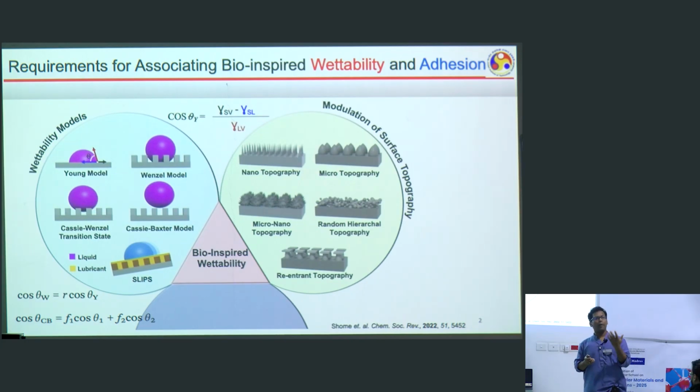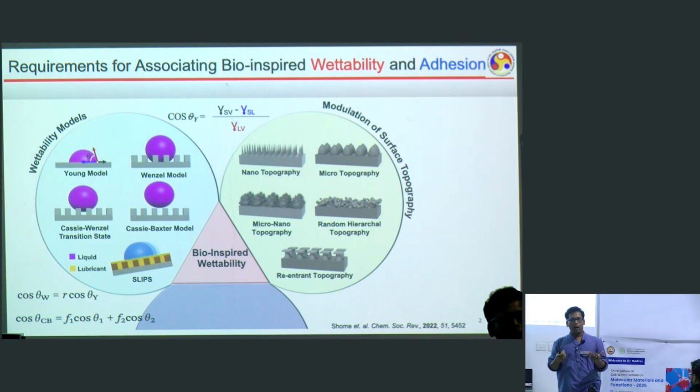But you might want control over the adhesion of that water droplet for some other purpose, but not at the cost of compromised wettability. The interface continues to display superhydrophobicity, but you want it to allow the droplet to roll only at a higher tilting angle, so that you have more control over the rolling of the droplet, with no loss when transferring the droplet from one place to another. That basically gives more freedom in terms of open microfluidics. That is another segment.